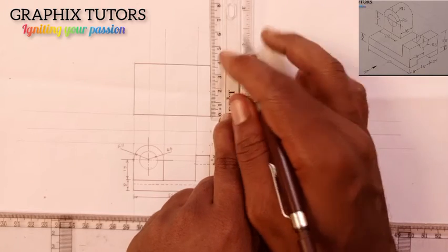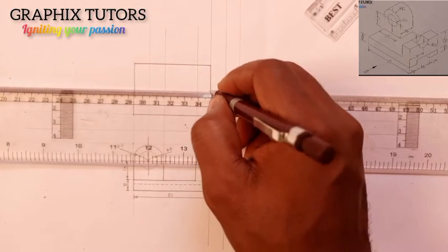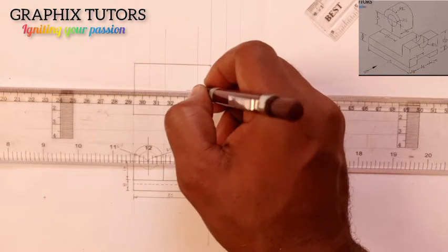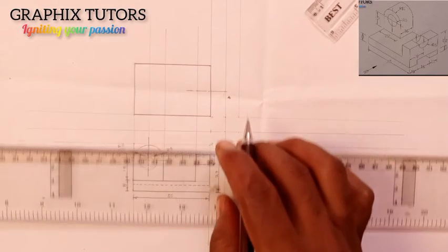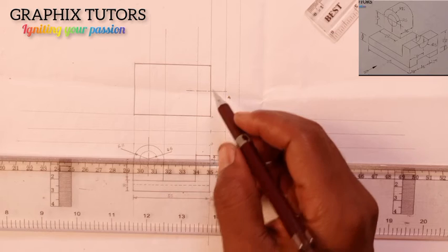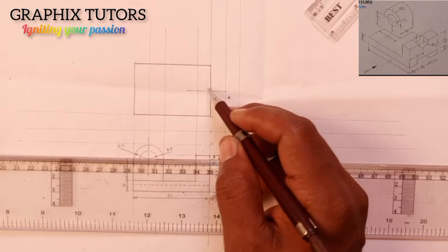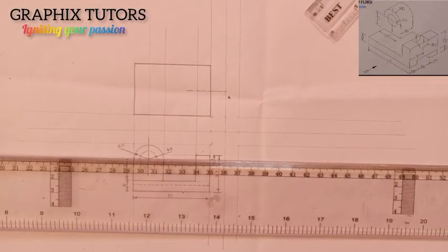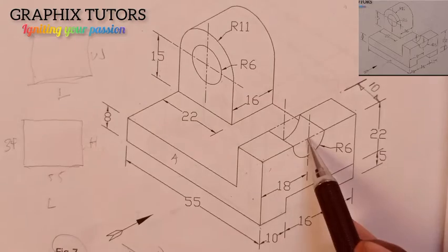Right? So I'll just take my meter rule, my T-square, and I'll just show a center line here at this point. So that is the center line. This is where I will now measure 6 up, 6 down, because with the radius of that cut here, this cut I'm talking about, I've already got in the center, which I said is 18. So I want to draw this cut.